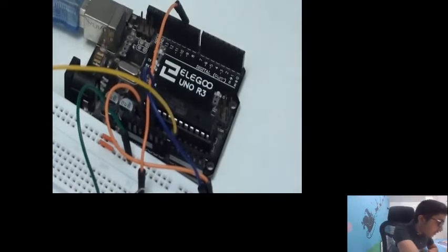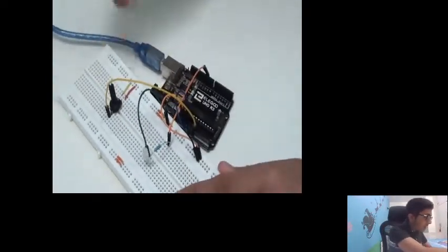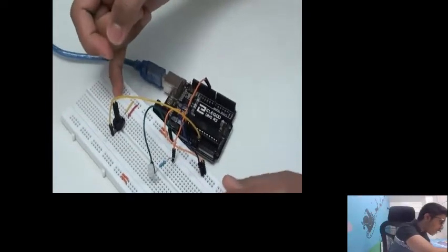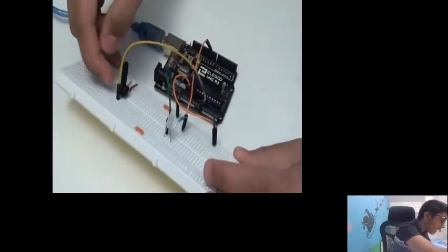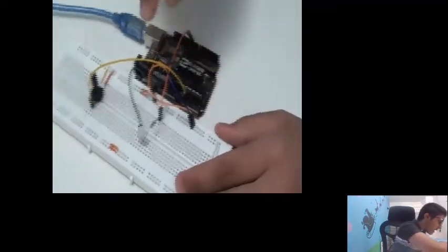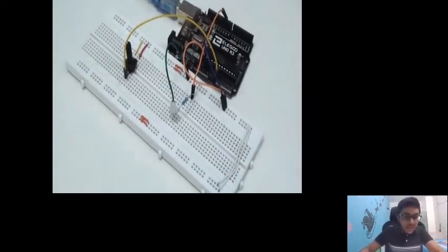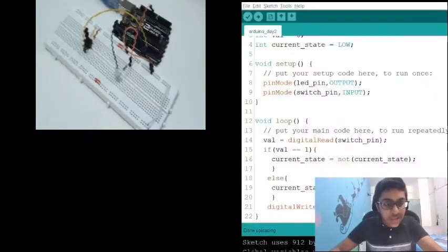Let's just make sure we have all the connections set. Positive, negative. Again, be very careful with these connections, especially the positive and negative. Make sure you're connected to the right rails. We've connected the analog pin to A0. We have provided power to our whole circuit, and we have connected our LED. Alright, sounds like we're good to go. Let's go ahead and code this thing.